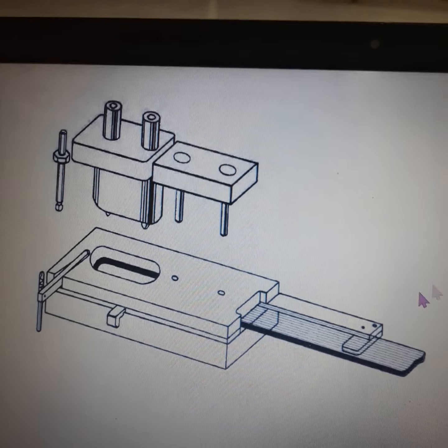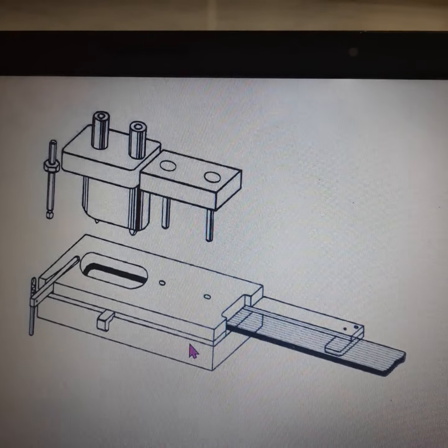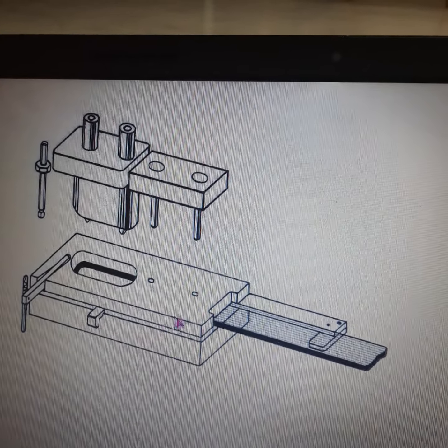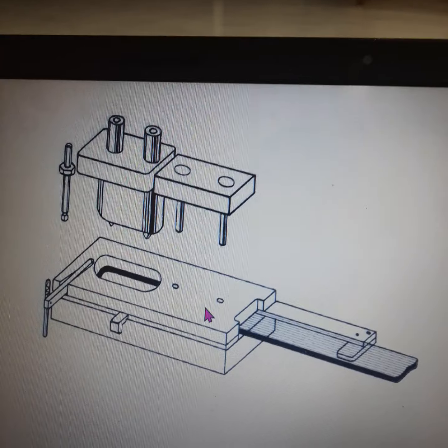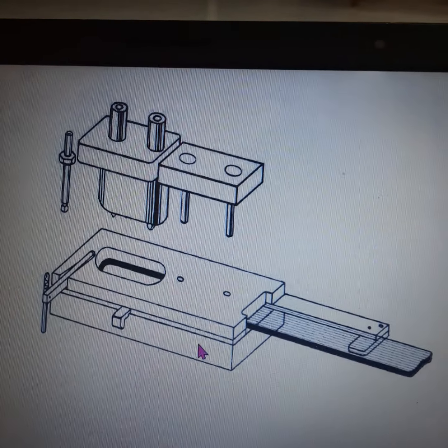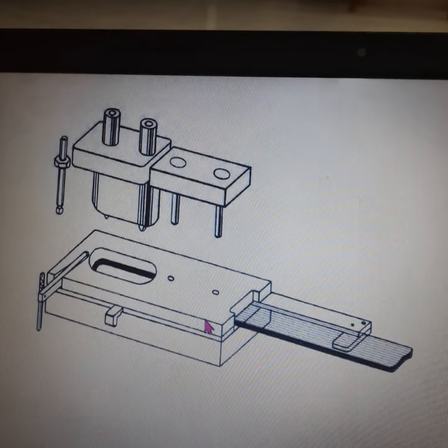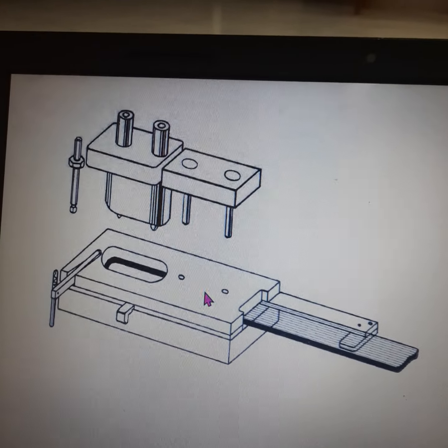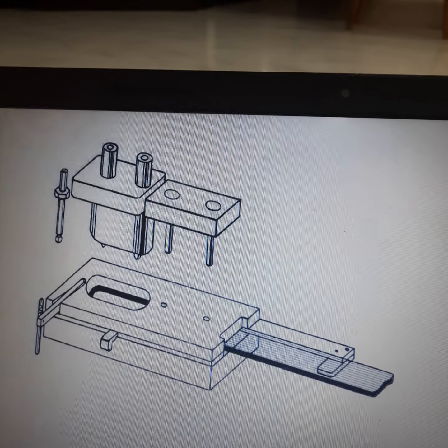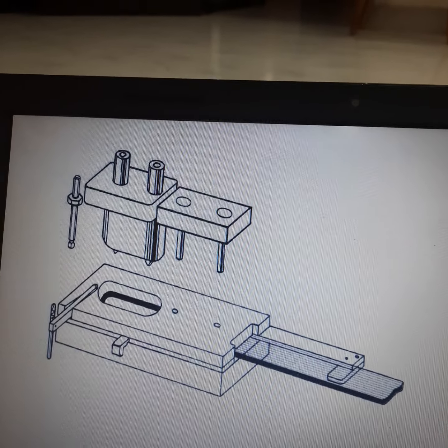So stripper plate is placed over the two gauges, front gauge and back gauge. Over the front gauge and back gauge, a stripper plate is placed. So this is another member to be added onto the press tool. So the stripper plate is one of the important member. The function of the stripper plate is to strip out the feed strip during the upward movement of the punches.